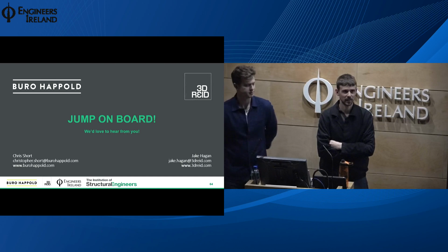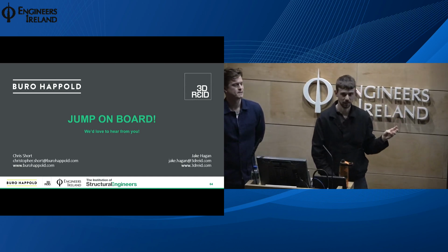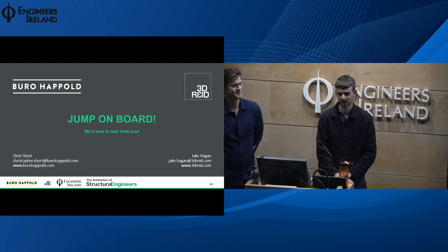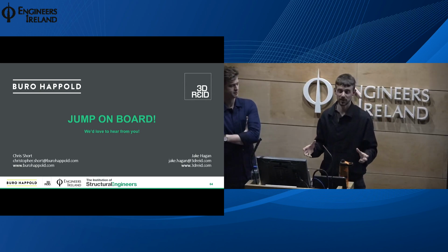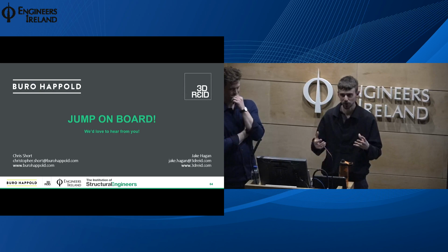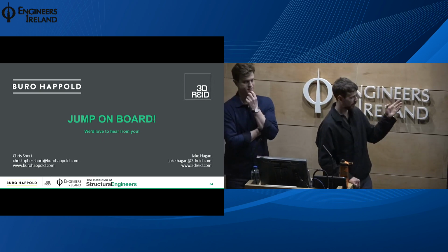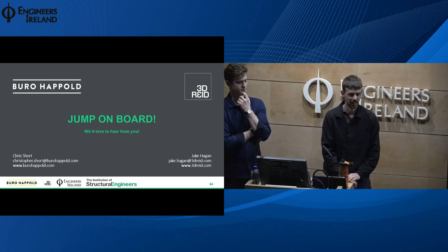And I do find that adding components such as fire barriers will increase file size, but not anywhere near as bad as general bad modelling practices will. So I think it's about having QA processes in place and an approach to modelling components, and an understanding of the level of information and detail that's required for certain stages. A fire barrier can be justified as being important enough to be 3D modelled.